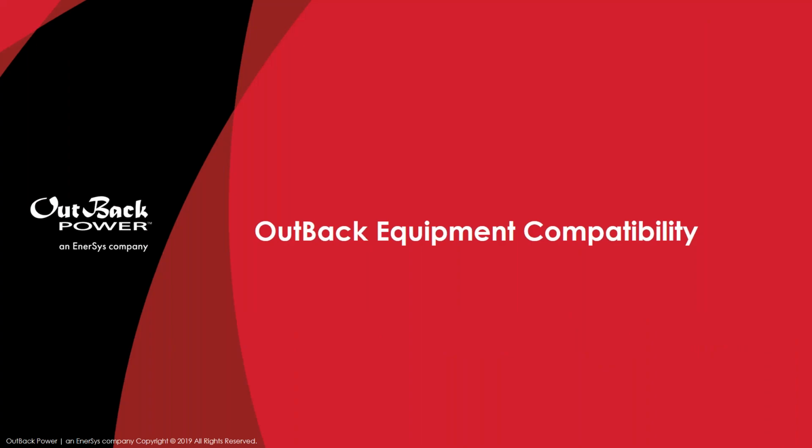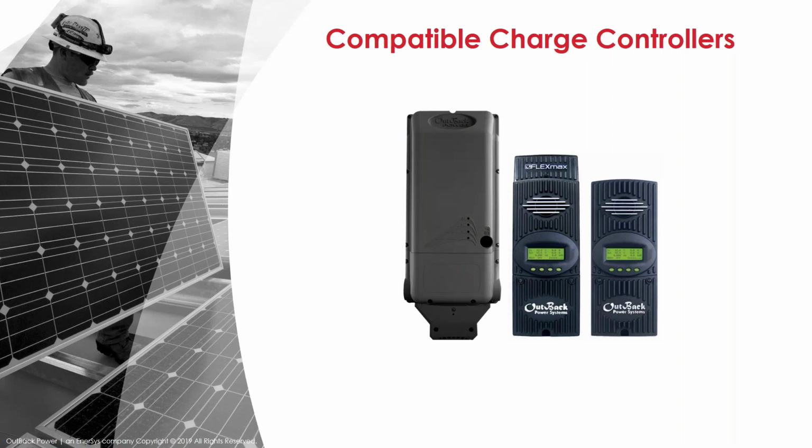Okay, so now we're on to OutBack equipment compatibility. And we'll first start off with our charge controllers. Any of our charge controllers are compatible with lithium except for the old MXs. So as long as you have a FlexMax FM100, 80, or 60, you're fine. It's completely compatible.